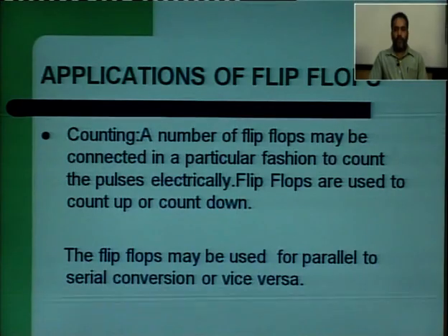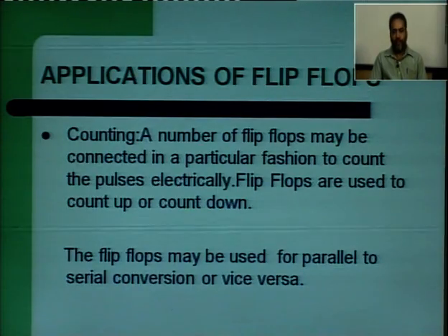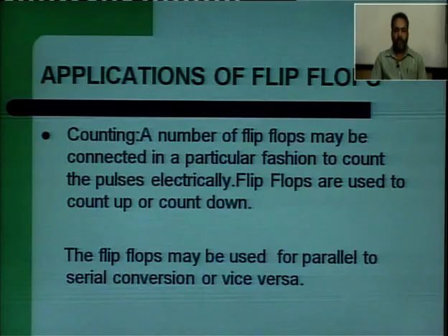So, this was all about flip flops. Here, first we discussed what sequential circuits are, then we discussed the types of flip flops. Then we discussed the latch, the basic concept of flip flops. Then there were flip flops. In this, first we discussed the SR latch, then the gated SR latch, meaning the SR flip flop, then JK flip flops, then the race around condition, then the master slave JK flip flop to resolve the race around condition, and lastly the applications of flip flops. So, this was all about flip flops. Thank you.